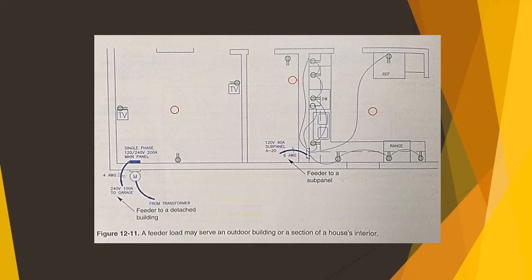Another example of a non-coincident load may take place in a residential garage or workshop. Most power tools in this situation would be used one at a time. The tool with the largest load would be used to calculate the voltage or the volt ampere requirement.